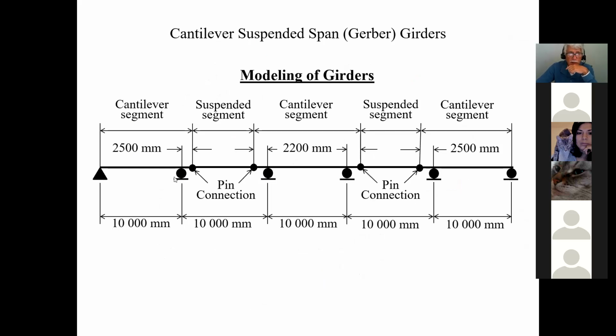Now, if you happen to put pin, trust me, it doesn't change much in terms of the analysis. It won't have a great effect. But if you put fix, that is totally wrong, and your analysis is going to be totally wrong. But I do recommend that the more conservative thing to do is to put a pin on one, for one reaction, one column here.